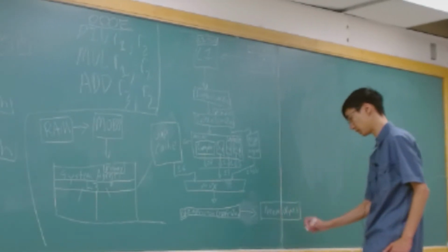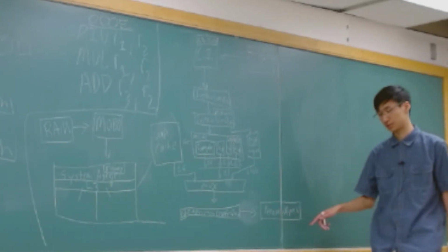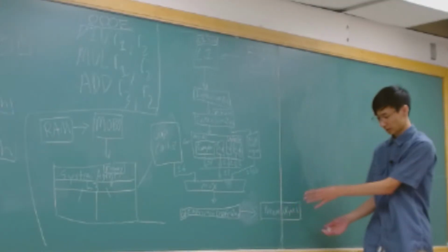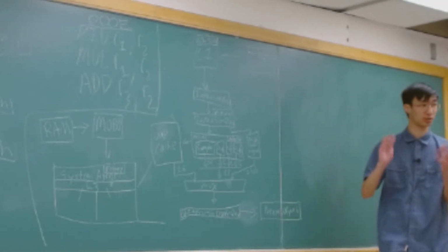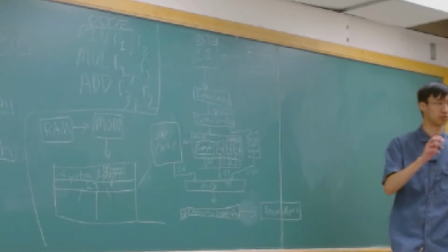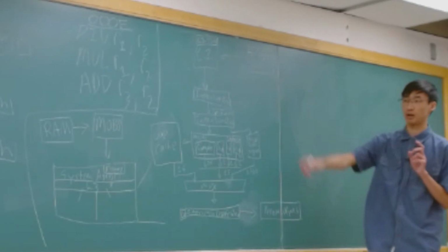So this unit here, called the rename dispatch unit, will pull instructions out of the decode queue, which has like 128 entries. And it does all of the coordination, right? It's kind of like the CPU of the CPU in the way that it manages out of order execution.